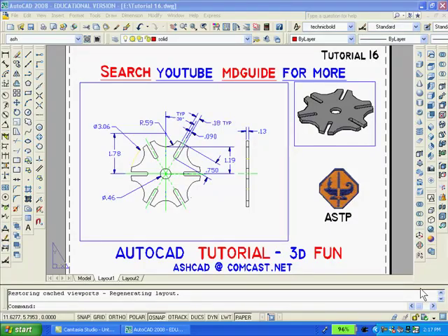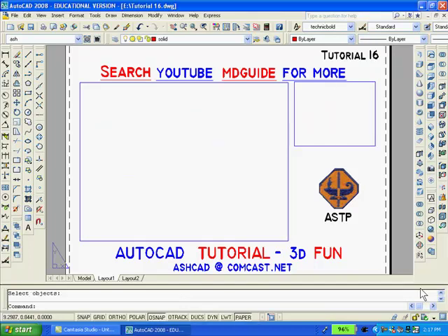What you are looking at is my 2D drawing and solid model in Paperspace. The first thing I'll do is erase both the large and small viewport. You can see that the drawings disappear from Paperspace. All that remains are two rectangles which I drew previously to serve as templates for when I redraw the viewports later on. To get into Model Space, I'll click the Models button.